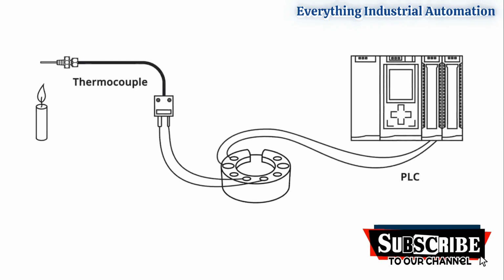All right, now that we've talked about sensors and the physical properties that they can sense, let's discuss how they are used in the industry. Almost every sensor used in process control will be connected to a transmitter because a sensor's output needs to be conditioned or amplified. Here's an example.